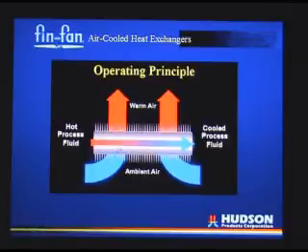For general information, for a 1-inch tube, the area ratio between the fin tube and the bare tube is about 20 to 22, in terms of whatever units you want to work in.